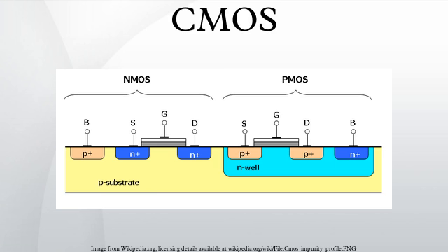These do not apply directly to CMOS since both supplies are really source supplies. VCC and ground are carryovers from TTL logic, and that nomenclature has been retained with the introduction of the 54C/74C line of CMOS.